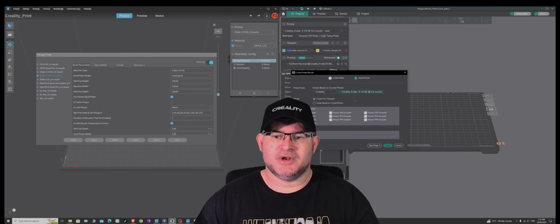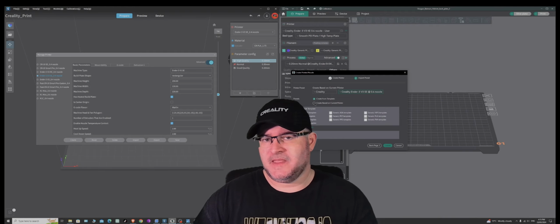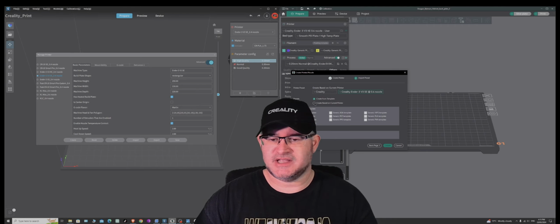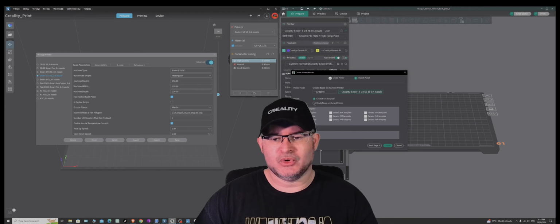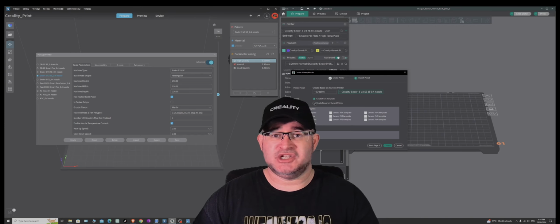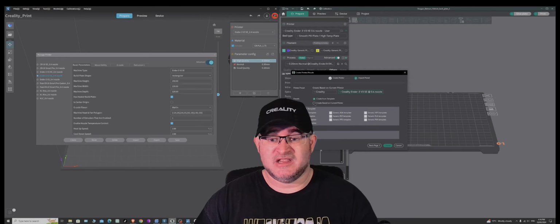And then what we want to do is create. You can create it based on a current printer, which we don't have one in there, or you can if you want to. Sorry, my mistake. If you have a profile, just quickly touch on this, it's important. If you have another printer that is a similar printer, say for instance, it has the same build volume and it's the same brand, it doesn't necessarily need to be the same board or CPU chipset or anything like that. As long as it's the same build volume and you're running the same nozzle that we entered prior, you can simply hit that and that will allow you to modify the G-code for, say, if you put in a KE model instead of an SE model. Then you can simply adjust the acceleration settings, edit the name, and you've basically got an easy way of doing it as well. So that's another option, but we'll just do it manually.